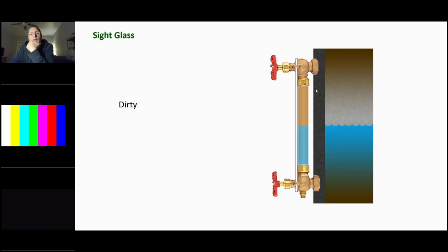And then you can run into what's a dirty sight glass, and that is any type of rust or oil that has accumulated throughout cycles, and it tends to show up in the gauge glass. So we've got a dirty gauge glass. That means we have to skim that boiler, and there are skimming procedures out there. We can get you information if you need that.